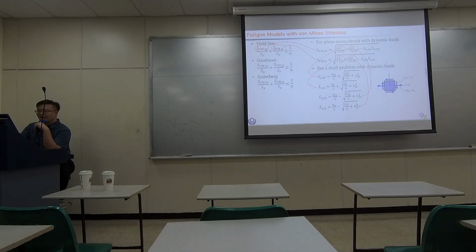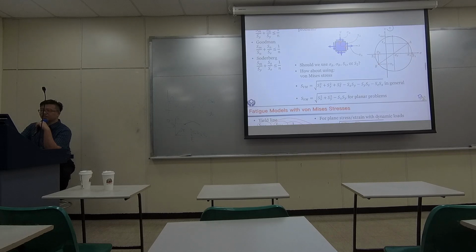Okay? Now, how do we get the mean value of stress in x and the mean value of the stress in y? We actually check the Mohr circle, and we realize the mean value of, this is like S1, this is like S2. So the first principal stress and the second one. So we can compute those by the general equation, where you try to compute S1, right?